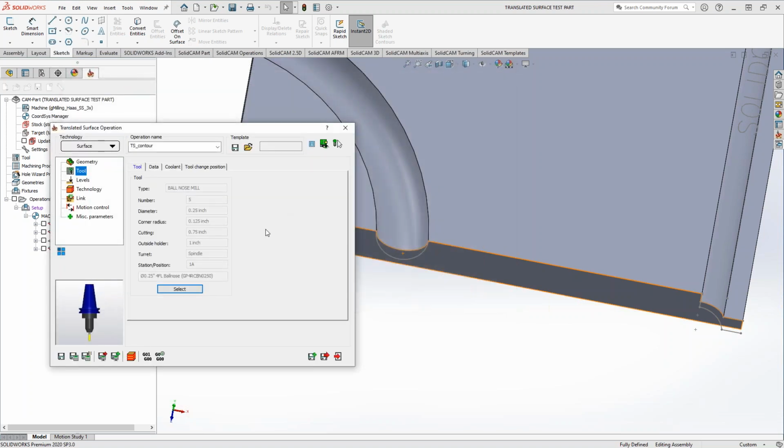Essentially anything you would use for roughing or finishing, almost. You're not going to be able to use a drill here or a tap or anything like that. So it's very, very simple in that way. A lot of this functionality is going to be very similar to profile in that you're going to give it offsets, you're going to tell it left side, right side. So that same sort of methodology carries over, even though this is somewhat of a 2.5D toolpath approximating a 3D toolpath, it still has a lot of that same sort of 2D, 2.5D methodology and nomenclature.